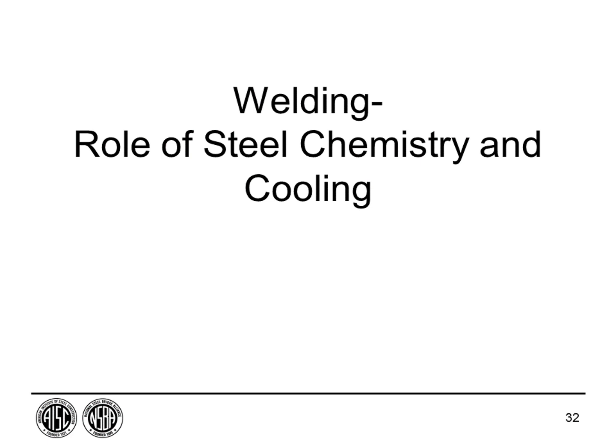So let's look at this relative to the welding. It's very important to understand that the reason we have chemistry controls on the plate material is so that we can weld it. We need to control that chemistry to provide a steel that's weldable. If you look at the relative difference between the specifications for reinforcing steel versus structural steel, you'll see much more chemistry control on the structural steels, and that's to provide the weldability and the other properties that we want.